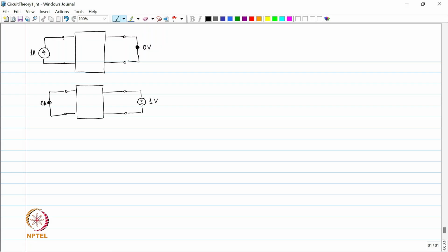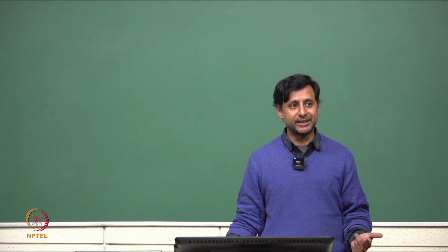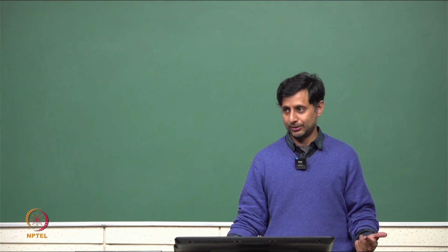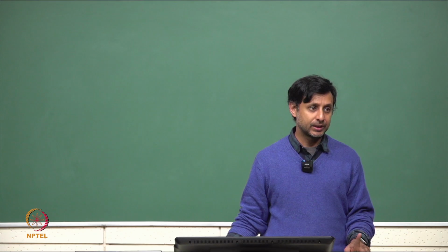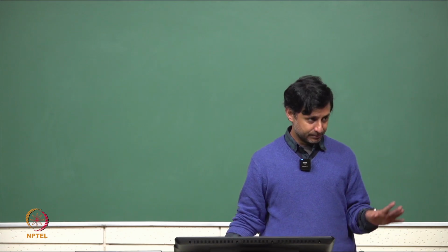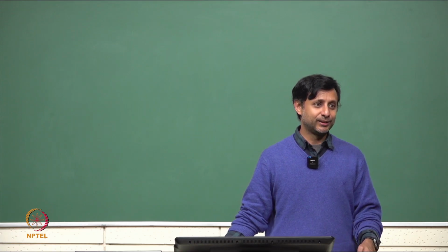Now, whenever you are working with Tellegen's theorem, please be careful about the directions. The direction of the current has to align with the direction of the voltage when you make the measurements before you do the dot product. Okay. Be careful with it, because a mess there is going to lead you surely to the wrong answer.